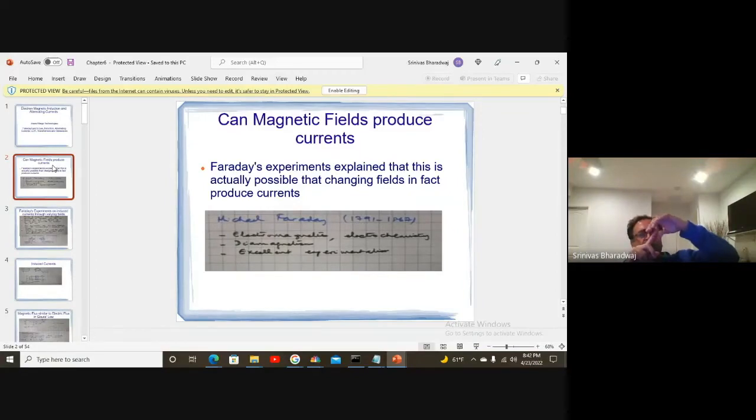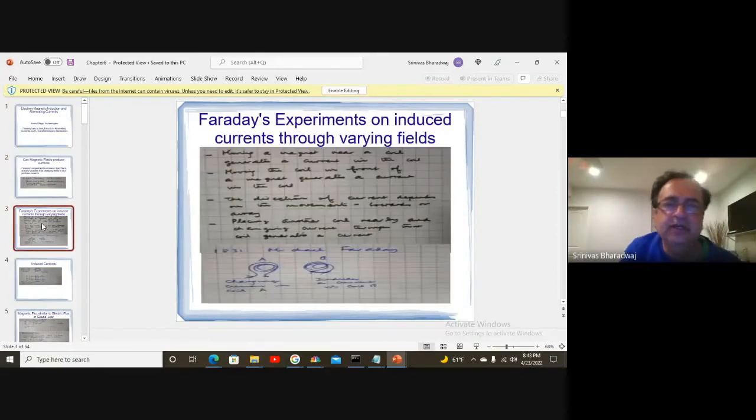When they move the generator, what does it do? The generator spins. Okay, when the generator spins, right, it produces a changing magnetic field. There's an electromagnet or a magnet inside that dynamo. Okay, it's called a dynamo. Now, what does that do? It produces a changing magnetic field, a time varying magnetic field. When you have a time varying magnetic field, then you have an induced current.